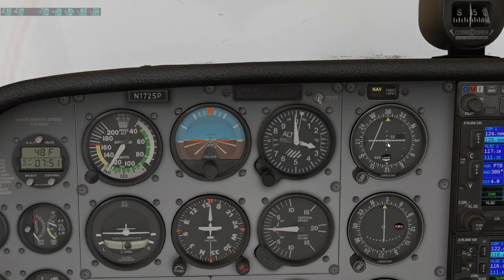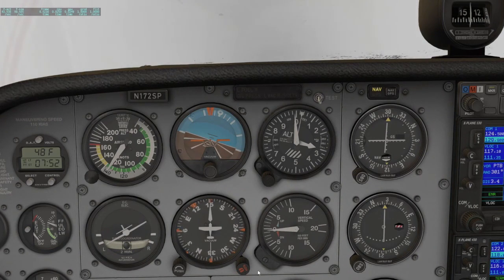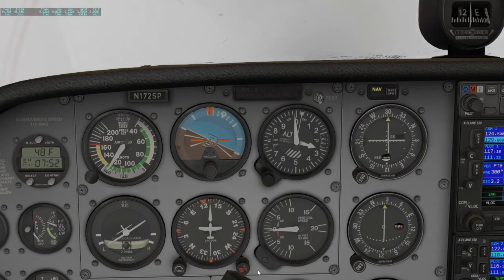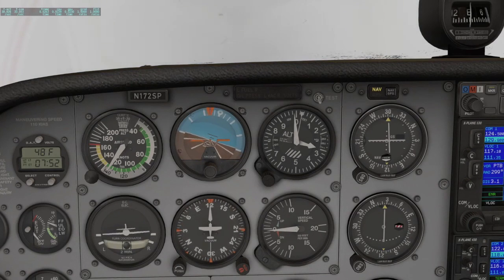Okay, now we're back again, and the needle is starting to move, and we're going to intercept a 300 inbound, which is direction 120. It's time to turn slowly as the needle is getting close to the center. Here we go. We start turning now. Okay, it escaped a little. It's okay, we can adjust by moving a little bit farther this way until it comes back to the center, and then we go back to direction or heading 120.